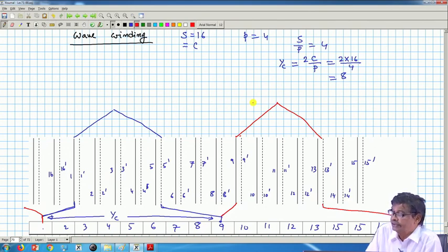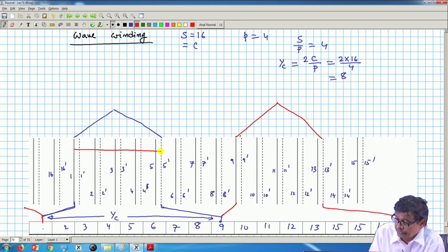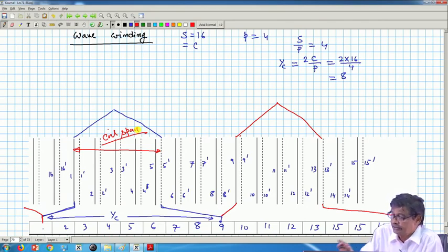Therefore, we will see that we have to make a little bit of compromise to implement the wave winding when we try to use a full pitched coil span, that is 4 we chose as coil span. At least we conclude that this way, if somebody tells me to complete the winding, it is not a better solution, only 2 coils and everything is over. So, we will continue with this in the next class.